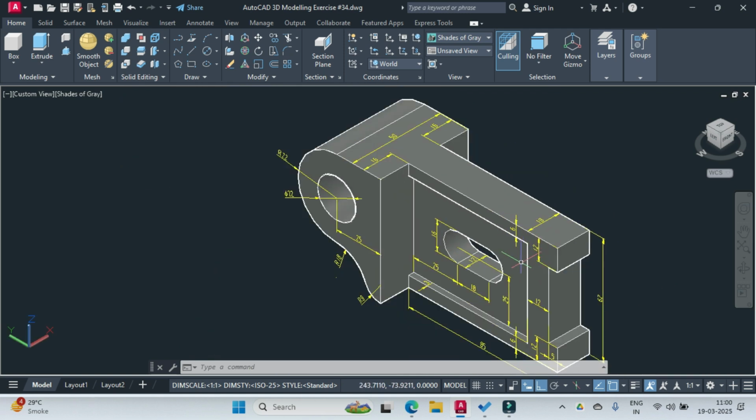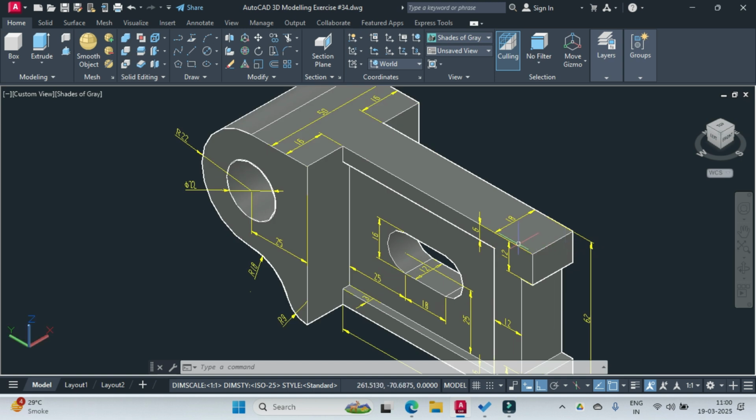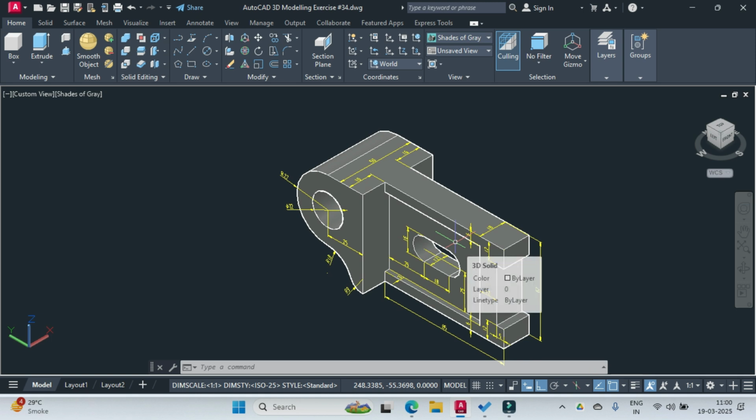And then we'll select this inner rectangle, press pull it 12 units, and outer rectangle, press pull it 18 units. Then move both these parts 16 units from here, so it will come in the center of this. And then move this part 3 units from here, so you get this cap. And our geometry would be complete. So let me show you how we'll proceed with this drafting.